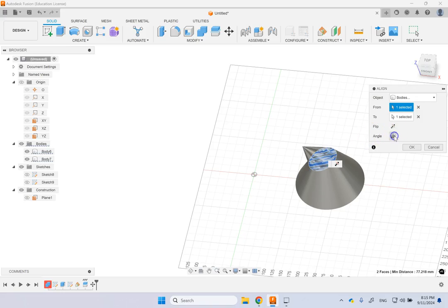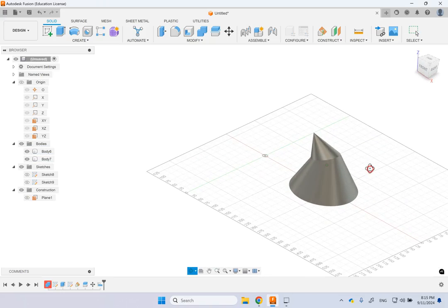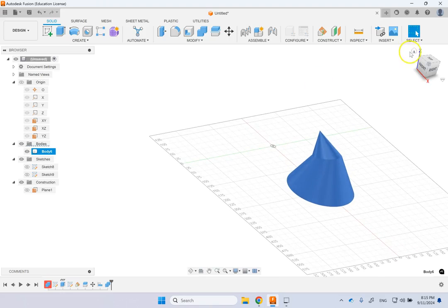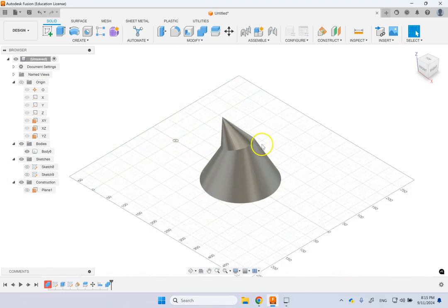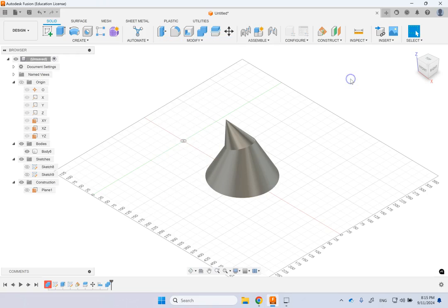And you can rotate them also in place. So look here. You can make this interesting object. Did you see that? I cut it. I made it like that. And now they are two separate objects. But guess what? I can pick them and I can combine them. Join. There we go. Now I have this single object. So I could go from this to this one. You see that? Powerful, huh? Very easily you can just split, you can align, you can rotate, and you can join back, and you can make something completely different.